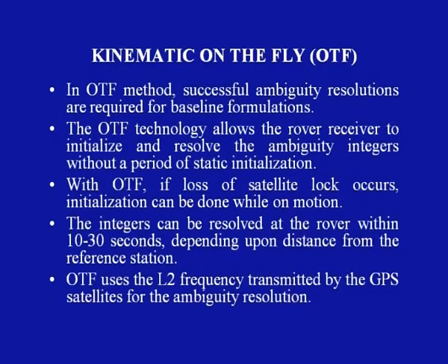In the OTF method, successful ambiguity resolutions are required for baseline formulations. The OTF technology allows the rover receiver to initialize and resolve the ambiguity integers without a period of static initialization. With OTF, if loss of satellite lock occurs, initialization can be done on the move. The integers can be resolved at the rover within 10 to 30 seconds depending upon the distance from the reference station. OTF uses L2 frequency transmitted by GPS satellites for ambiguity resolution.